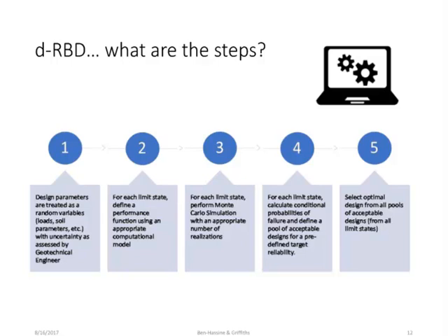Then for each of these limit states, we generate realizations in a Monte Carlo simulation framework. I will go over later how many realizations you're probably going to need. Then you do some statistics on that and come up with a design. From all these limit states, you come up with an optimal design, which is the least cost design meeting all the limit states being considered.